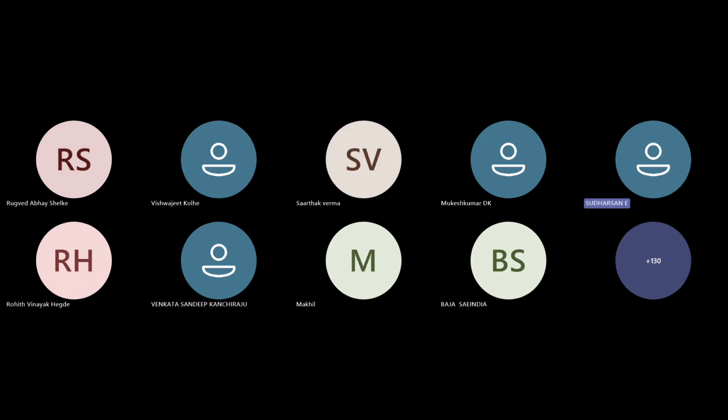Bro, can I tell one thing? Yeah, yeah. Teams, if you are getting any errors while putting the FR with respect to FR1, you can create the FR1 coordinate system in your assembly model with respect to the overhang and the graphic model provided in IPG. Then with that coordinate system you have created in the assembly on the rear side of the vehicle, take all the values from that perspective so it will be more accurate, and you don't get any errors while entering data.